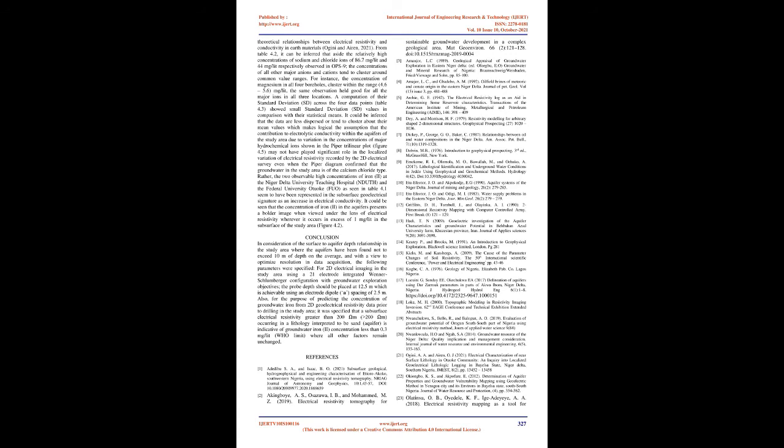The water-bearing horizon at the Niger Delta University Teaching Hospital Profile 1, NDUTH 1, occurred at a depth of 9 to 12 m with fine to medium sands as lithofacies, Table 4.2. The observed resistivity fell within the range 64 to 104 Ωm corresponding to an iron concentration of 1.48 mg/L, whereas all other chemical components are observed to be relatively low in comparison with WHO standards, Table 4.1.